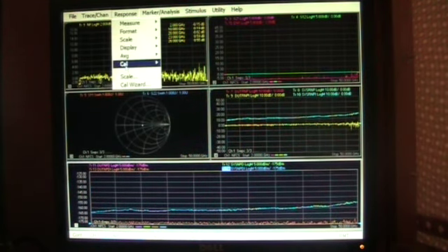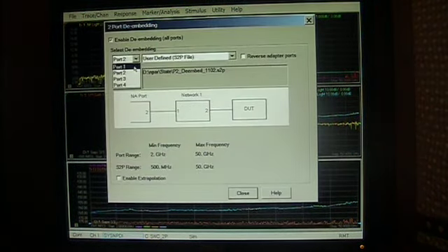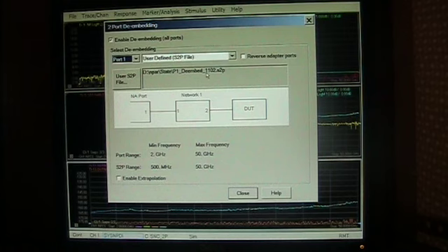I wanted to note something here. Let's go back and look at the fixturing, 2-port de-embedding. Now with port 1, we've selected the port 1 de-embed file that we created. This file is only valid for when the tuner is in its initialized position. When we move the tuner to another position, we will need to place a different de-embed file in to account for the additional loss. We can think of it that way. That's what will happen during the measurement steps.